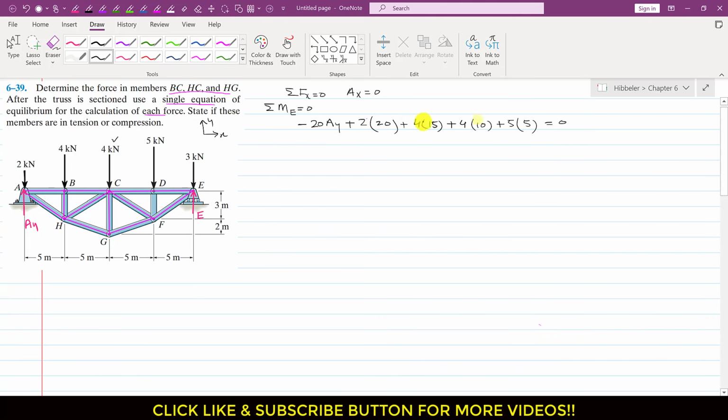And if I add up all these and divide by 20, that will give us AY, right? I bring this EY term to the other side, so we will have the equation like this. This will be 20 AY, right? And if I divide this sum by 20, that will give us AY, and when we solve it, AY equals 8.25 kilonewtons, right?